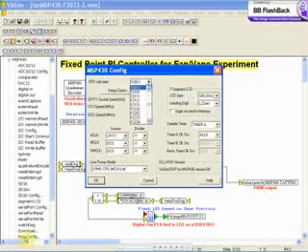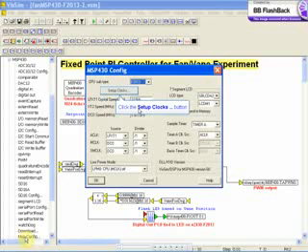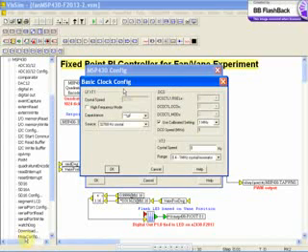For the MSP430 configuration, first select your CPU subtype from the list of supported parts. Next, set up your clock sources. Based on your selected CPU subtype, you have up to 3 independent clock sources to set up. 2 external, designated XT, and 1 internal, DCO.